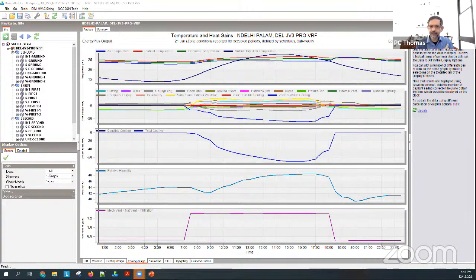So you need to do something before you supply the air for dehumidification, okay? If you're doing chilled beam systems, you have to be very careful because you can't let the temperature exceed the dew point in the space, because if you do, then you'll get rain in the space, okay?